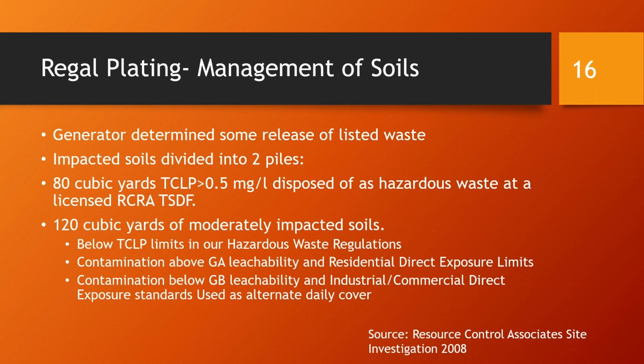So the importance of this is, I made a little reference to the contained-out policy that a state can make, and this usually has to be, I think in all the states in our region, in writing, that you ask the state for permission, even though it's contaminated environmental media that had a listed hazardous waste, if it's below the applicable remediation standard for that material, be it groundwater or soils, in this case soils, the state can issue a contained-out determination saying that that is no longer a listed hazardous waste. But this is something that needs to be done in writing from the state.